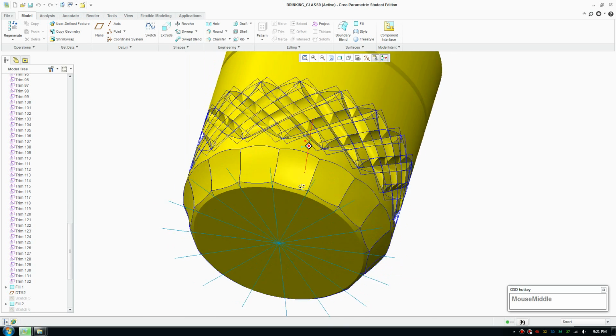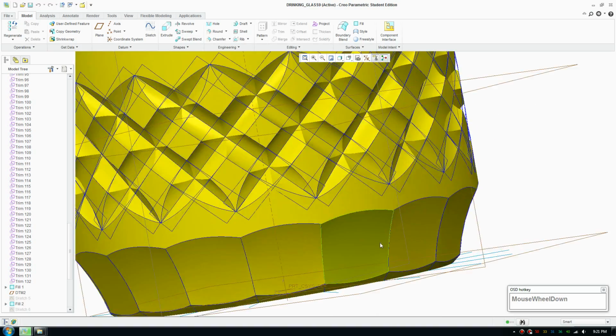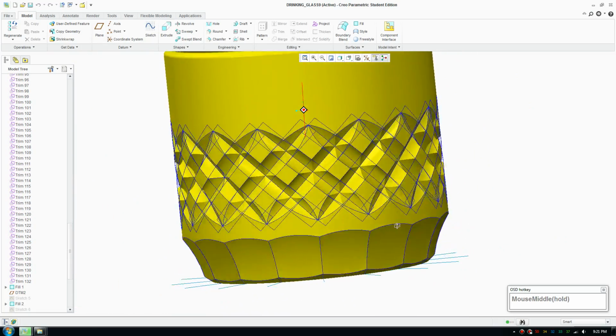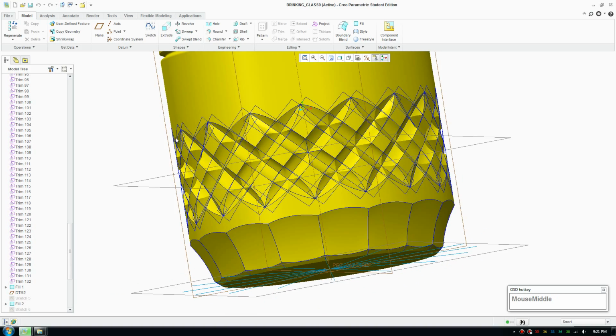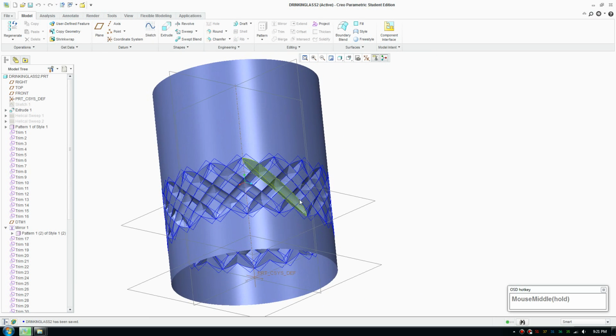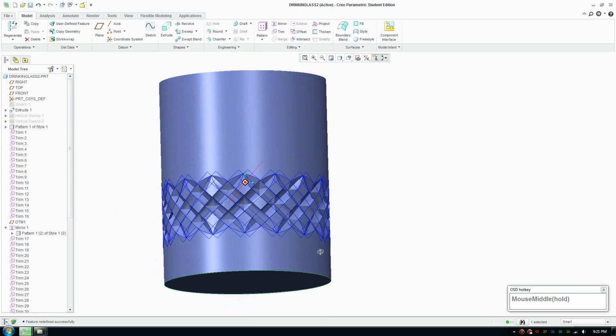So on the bottom of the glass there is a sort of concave surface on the bottom here, and I'll show you again with the style tool. You can create this nice effect, and I don't think you can create it in any other way. So yep, it could be very useful for you. Okay, now I'm just gonna cap off the end here. To cap off the end, you need a sketch. Okay, so select your sketch and click fill and it caps off the end there.